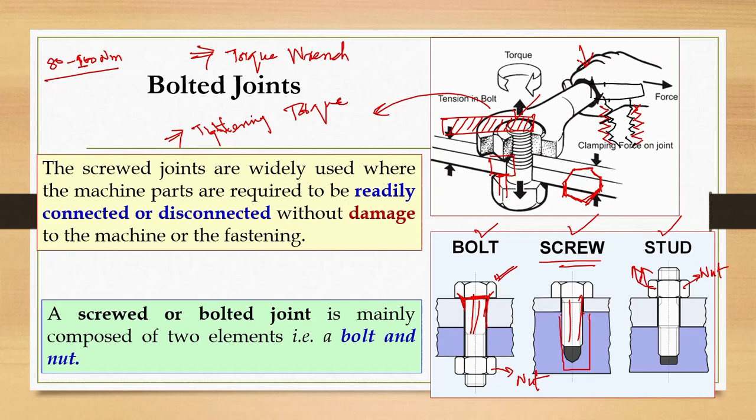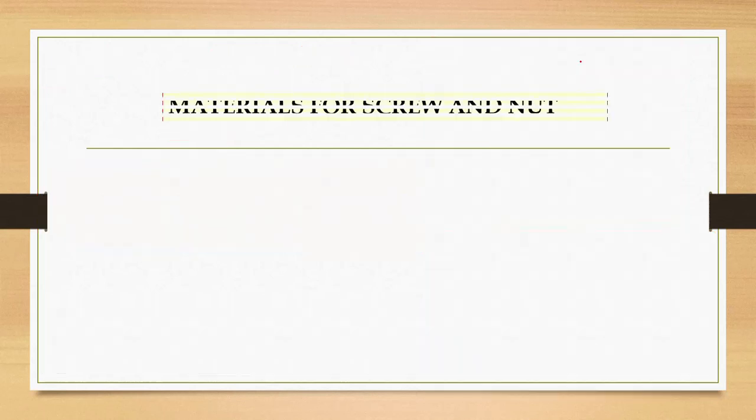That's why people generally use normal wrenches and apply hand force, where they don't even know what force is required, and they just apply as much force as they can to tighten a bolt. So yes, it actually affects the life of the bolt, especially if you're talking about bolts in industry.